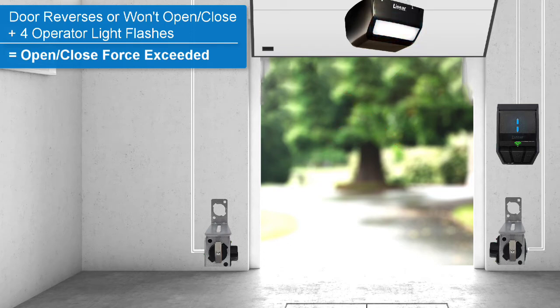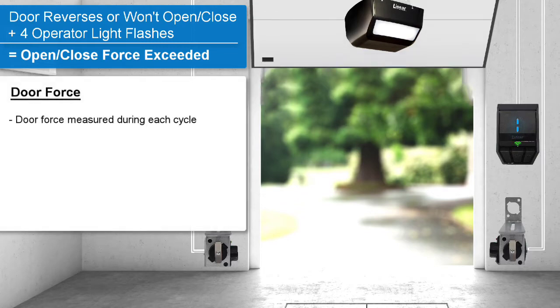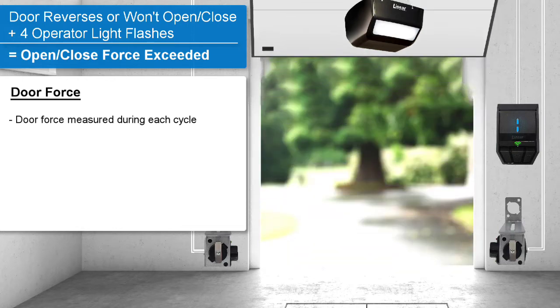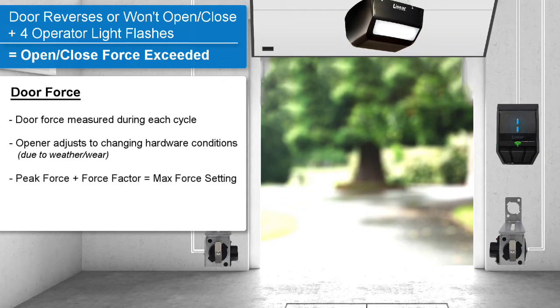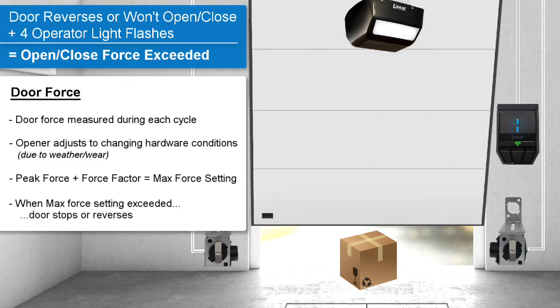Before we explain how to resolve this issue, let's discuss door force. The opener automatically measures the door force throughout the entire travel of the door each time the opener cycles. The opener will automatically adjust to changing door hardware conditions over time due to weather and wear. The opener uses the peak force, measured during each of the previous cycles, plus a force factor, to calculate the maximum allowed force setting for the current door cycle. If an obstruction causes the maximum force setting to be exceeded during the current door cycle, the opener reacts to the obstruction by stopping or reversing.